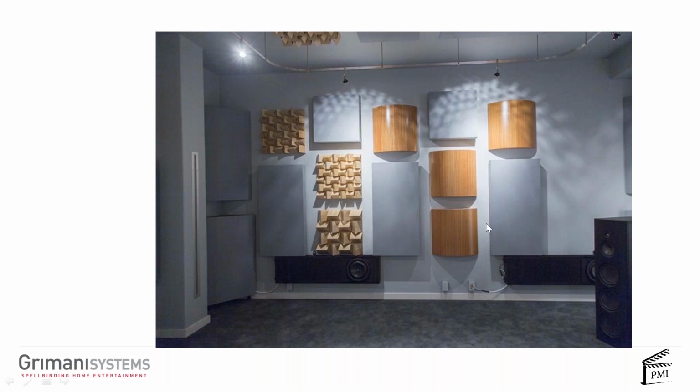So the real key is lay out the absorbers as evenly distributed as possible. Fill in with the diffusers. Make sure that there are not gaps that are much bigger than 6 to 8 inches between them, and you'll be fine.